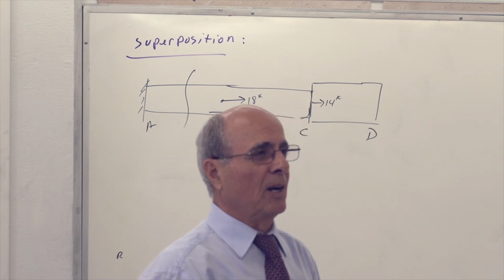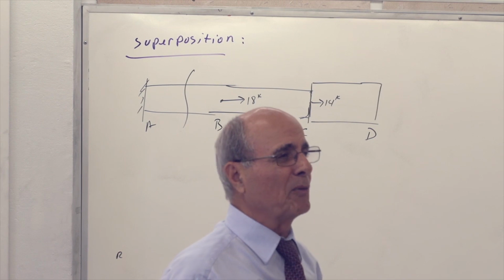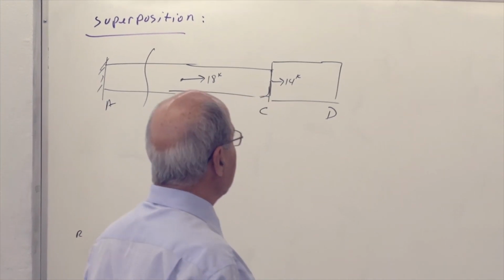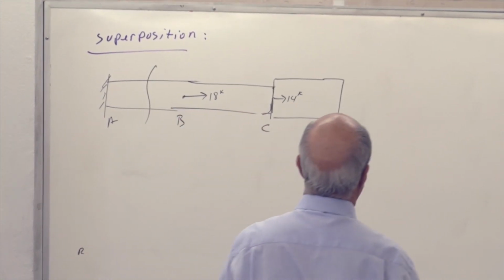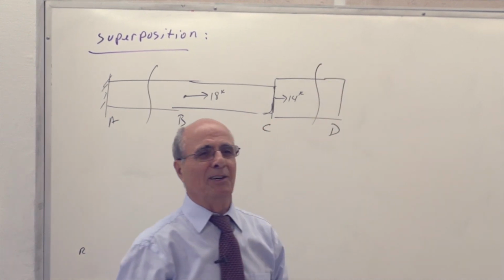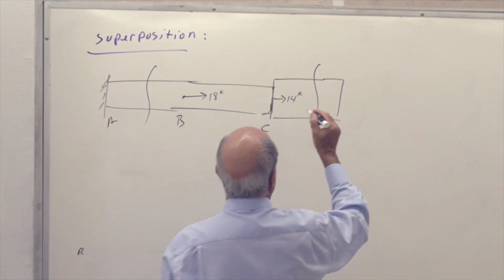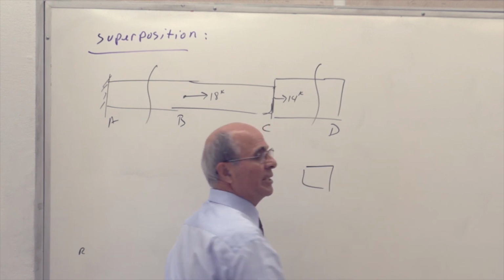Come on, guys. I hope you are not saying 18. Is that correct or not? What's the force there? If you are in doubt, start from the other side. What's the force here? What's the force there? I hope you say 0 this time. Is that understood? The 14 applies at C, so it applies to A, B, B, C. Everybody understand? The force in member CD is the internal force. Look, nothing there. Is that correct?